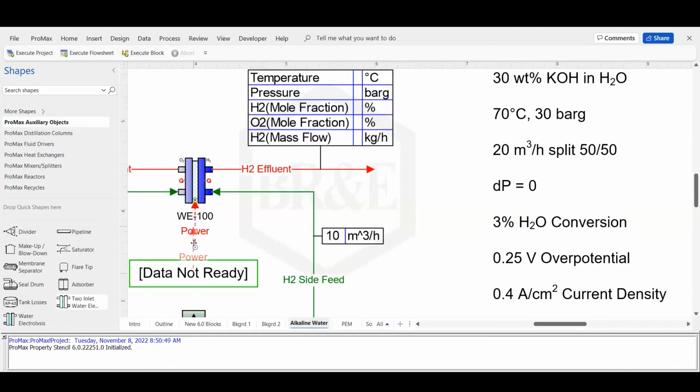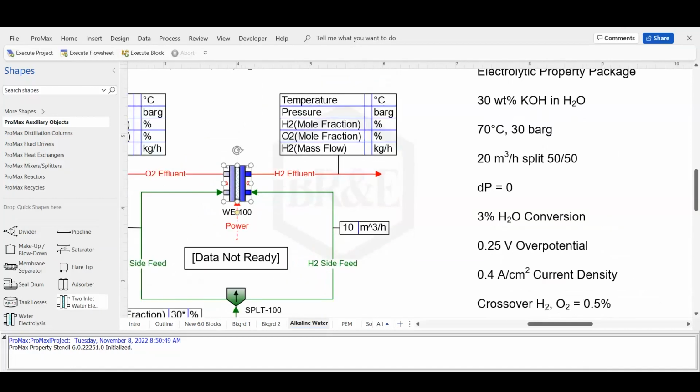There is a port that's got this little blue shape with a lightning bolt through it, or a kind of icon, and that is where you want to connect your electrical power energy stream. And then there's the option of adding or withdrawing some heat. So there's a place for a thermal energy stream to enter or be withdrawn from. And we'll use that when we go to the solid oxide case. So now let's go back to where we can see this better.